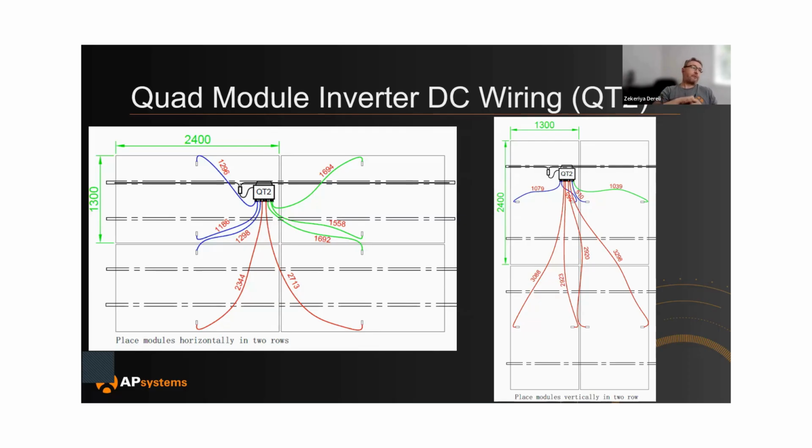So you're going to have DC extension cables, which we supply. Check with your Charge Solar sales rep and try to get the DC extension cables pre-made. You can make them in the field, but we don't really suggest that. You could have a bad crimp or some errors in the crimping, and making that cable causes issues later down the road.